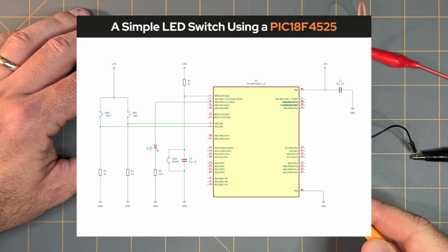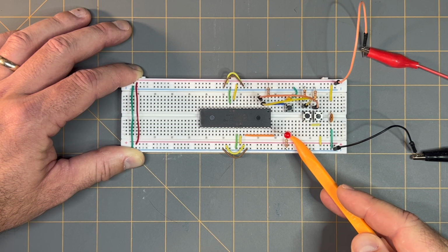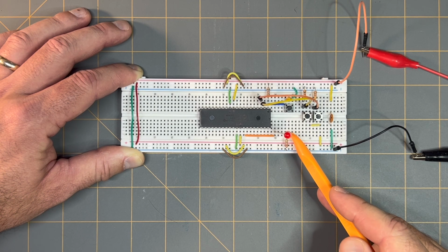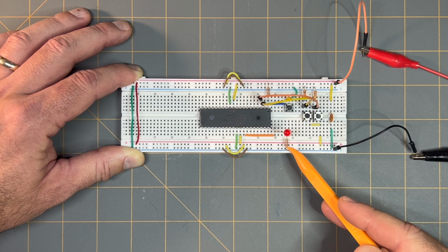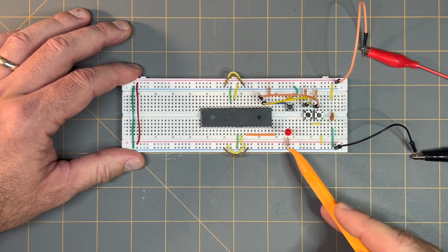This is resistor R3 as referenced on the schematic diagram, and I have one of its legs or leads in point J17. That's in line with the cathode leg or lead of the LED, and I have the other leg of this 220 ohm resistor going to an adjacent point along the negative power rail on this side of the breadboard.